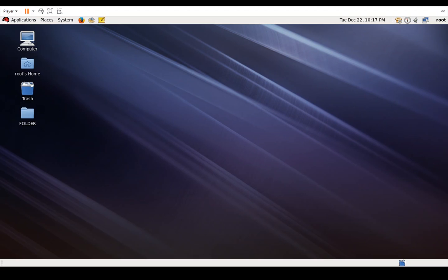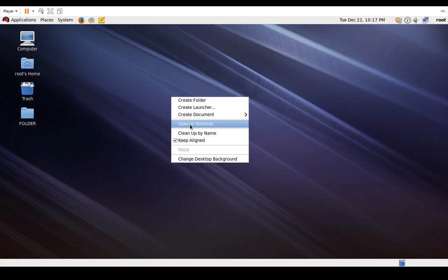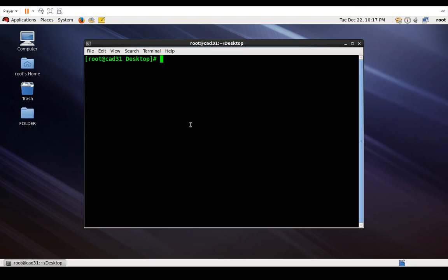Okay, so we will continue with the next topic. So open in terminal, csh, source. Okay, and welcome to Cadence. So for all the experiments, this is the first step. So now the command is Virtuoso. Okay, and press enter.